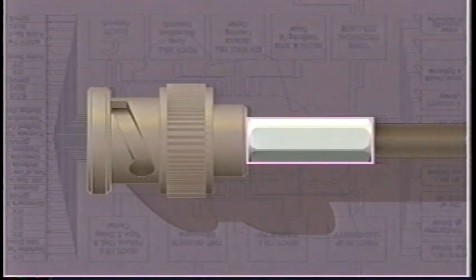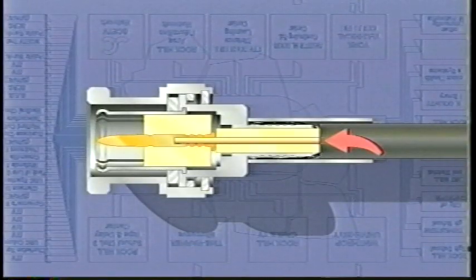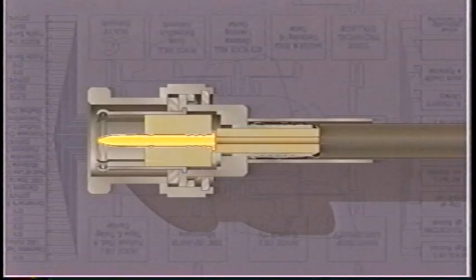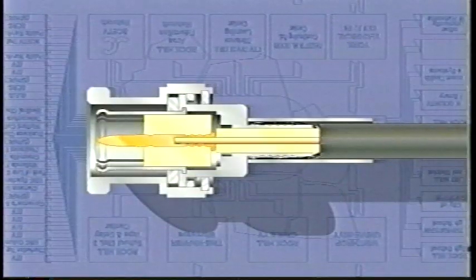The ends of the crimp sleeve have a step on the end away from the connector body to provide a finished appearance and to help retain the cable jacket under the crimp sleeve when the cable is bent close to the connector body. On the BNC connectors, the center pin depth relative to the connector end must be measured. The pin depth is important to ensure proper engagement with the mating contact. The pin depth is determined by a ridge inside the connector body and a groove cut into the pin.